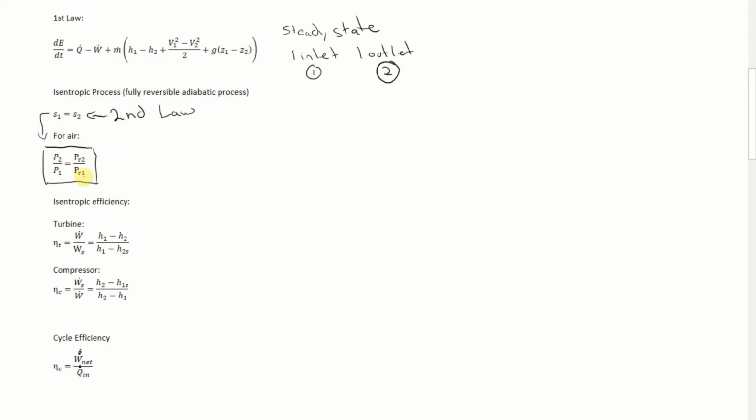Don't worry too much about understanding exactly what the reduced pressure means. We're going to use it very practically, and after a couple of times of using it, you'll understand how to use this at least. The Pr values you can find on table A22 in your textbook.